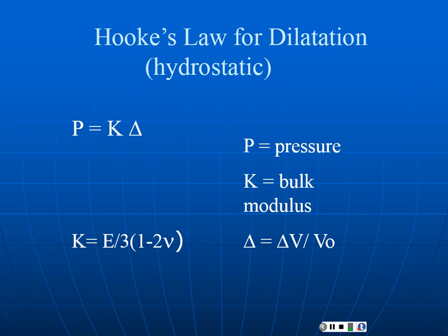Similarly, we have Hooke's law for dilatation. This would be the hydrostatic problem. And here we call K the bulk modulus. You'll run into K if you're doing acoustics work because a lot of times the speed of sound in an object is calculated, or the equations for that are given, in terms of the bulk modulus of the material. But again, if I know Young's modulus and Poisson's ratio, we can calculate K. We don't have to measure it directly.